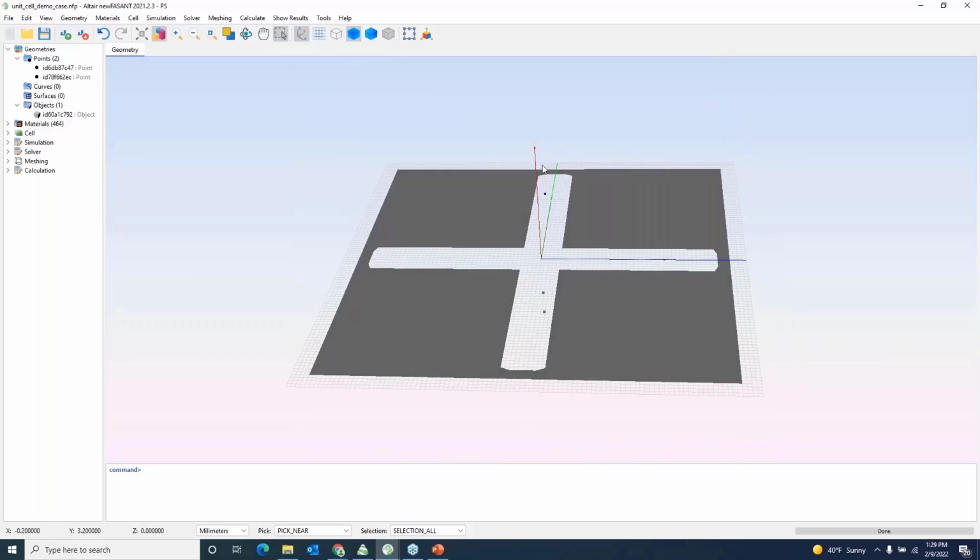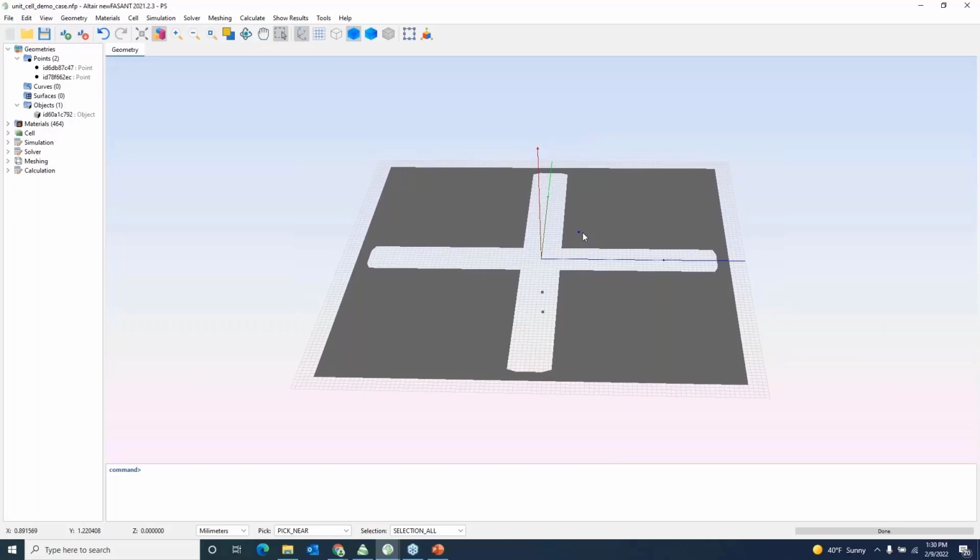Okay, you can see over here, basically, we took a metallic plate and we embedded the cross structure on the metallic plate. That means we have an air and metallic interface, metallic region over here. Okay, how can we access this particular thing? Let me go ahead and go to the cell options. All these options are available in the cell. You can see over here frequency selective surfaces. It's not only just the strips. You can also select rings, strips, crosses, any shape you want. You can get this particular thing from this particular FSS primitive cell.